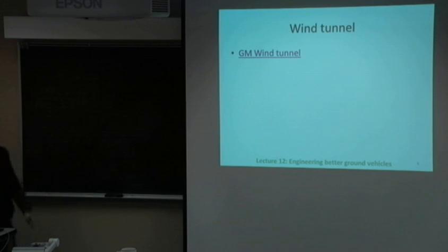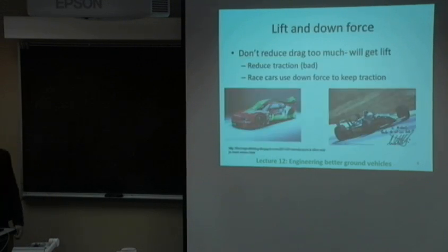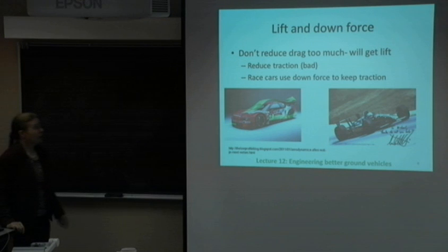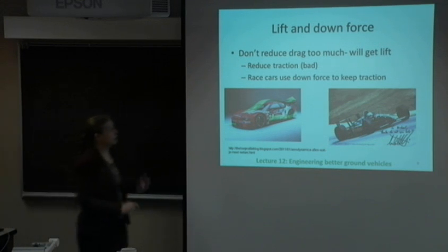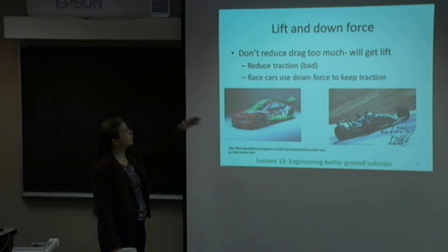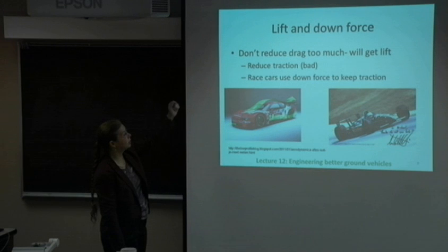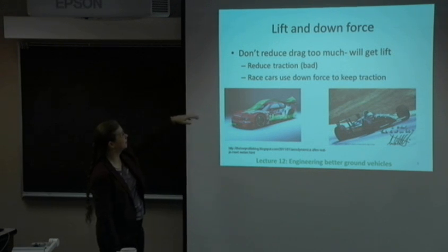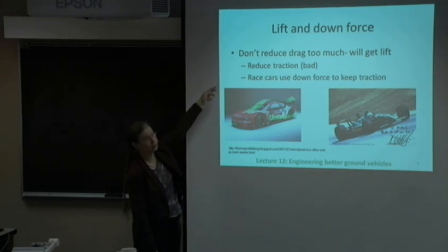There was something else I was going to say and I completely forgot, so maybe it'll occur to me later. The other thing about cars is when they're rushing through the air, you can create lift or you can create downforce. So lift is bad. It reduces the apparent weight of your vehicle, which could improve your rolling resistance and your slope business, but it reduces your traction, which is bad.